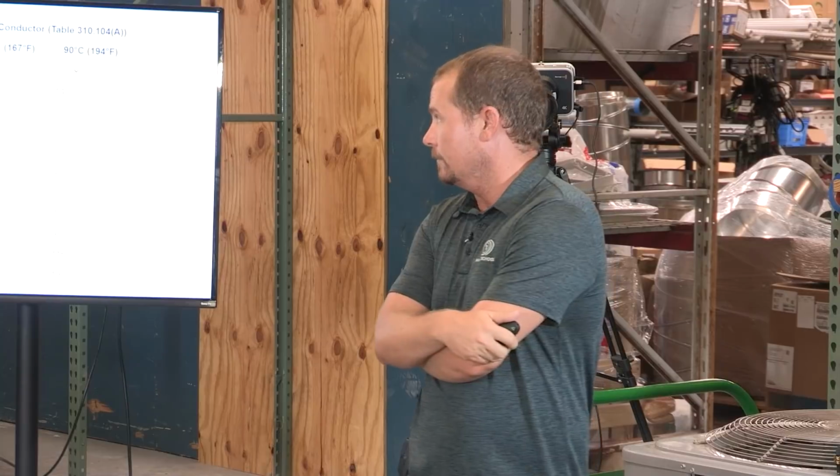And so a lot of times people will tell somebody they've got to rip the wire out and it's not the right size, it's undersized, when maybe it's not. Maybe it's all 75 degrees Celsius or 90 degrees Celsius. In commercial and industrial, you'll also see 105. So it can handle more. If you start to pay attention to wire sizing that manufacturers put inside units, you'll catch on pretty quick that it doesn't really jive with what we have to put in as it attaches to the appliance. They're using smaller wires, and that's because they're using better insulation ratings.